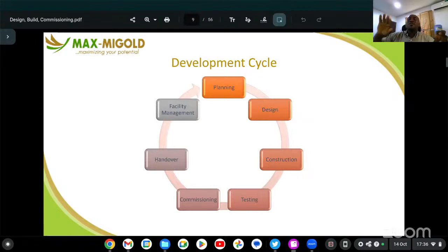So it even cut off the system for them not to be over. But there was an overflow for 1 minute, which is a problem. They don't want any overflow at all. You want the system to be seamless. Whenever they have low level, it peaks. Whenever it pumps to a certain level that it could serve the facility for probably 12 hours, it cuts off. There's no overflow at that point. But now there's an overflow. So they need to trace what could be the problem.